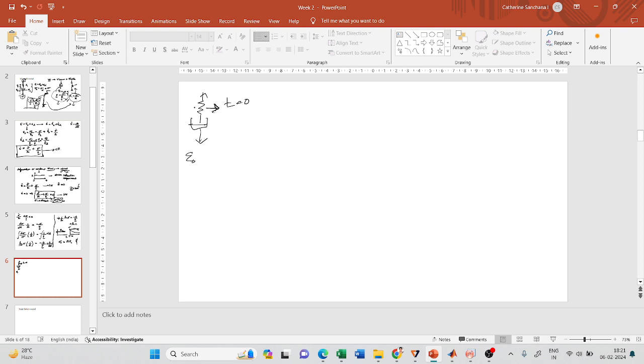Why am I saying that at time t equals 0, the contribution of the response will be only from the spring? It is because when I apply a deformation to the material, when we saw the properties of an elastic material, we saw that if it is an elastic material, it will immediately deform, right? So both will have a constant value. In the case of a viscous material, it will have a delayed response.